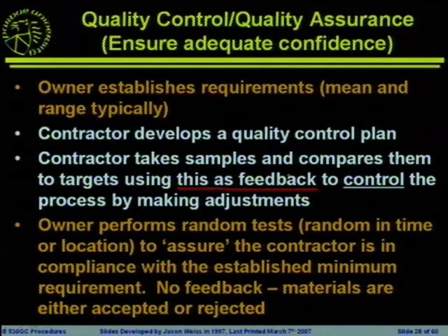This information helps you adjust your process, helps you adjust what you're doing, to control the process and to make adjustments. So we don't just take tests to practice taking tests or because we really love doing sieve analysis. We run these tests to help control the concrete that's being made. So if we see an adjustment in the fineness modulus, we make an adjustment to the concrete.